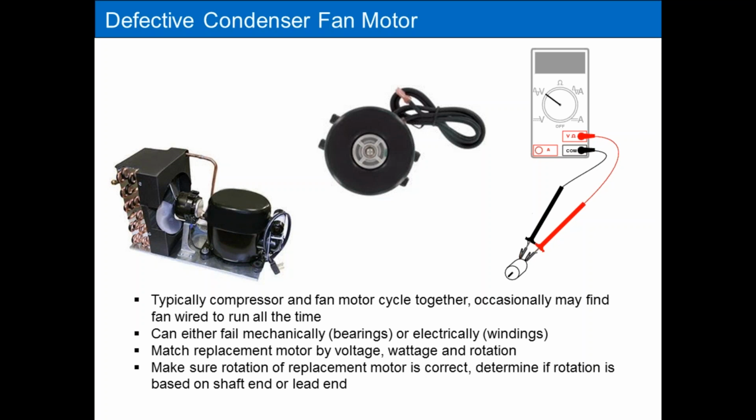So depending on your motor manufacturer, that's kind of tricky sometimes. What you think is CW ends up being CCW on your replacement motor. So verify that, and if you're using a non-OEM fan motor, make sure your replacement has the right rotation, and be certain not just to go by clockwise or counterclockwise. Make sure they're looking at it from the same orientation.